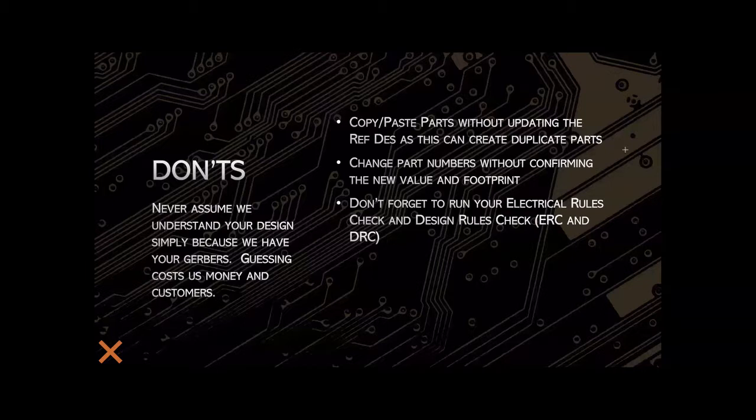And let's go over a quick list of don'ts. Very first rule is never assume that we understand your design simply because we have your Gerbers. Guessing costs everybody money, whether we as the board shop were wrong or you as the customer made an error, it's costing us money. The next one is don't copy and paste parts without updating your REFDES, as this can create duplicate parts.